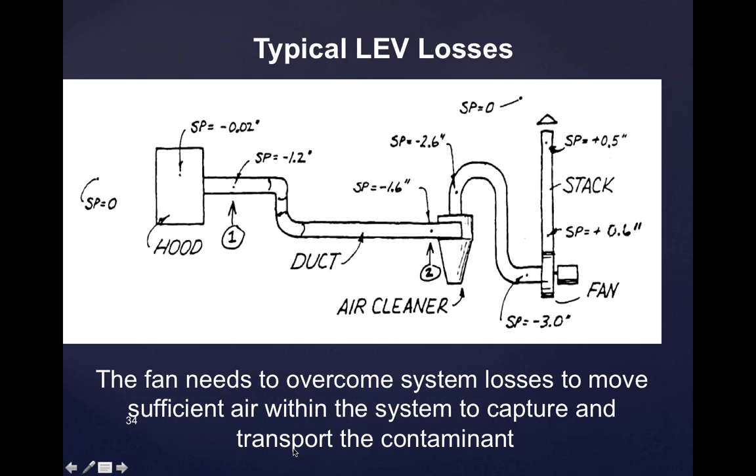Anybody know what that's called? It's contracting, right? Imagine that the flow looks kind of like a vein, like blood flowing. Remember the Latin term, vena contracta, ring a bell? Vein contraction. I think we'll have an illustration of that. There's an area of particular turbulence and energy loss right where you first enter the ductwork, because the air contracts away from the ductwork and you get eddies.